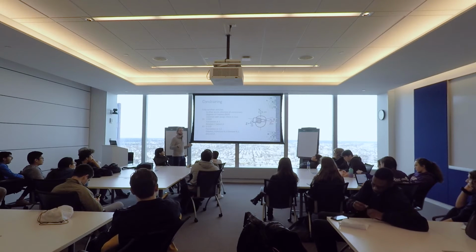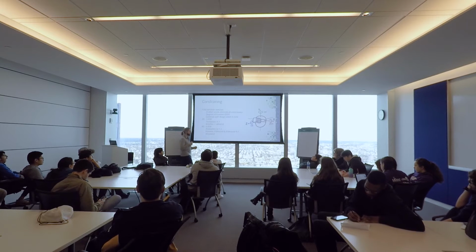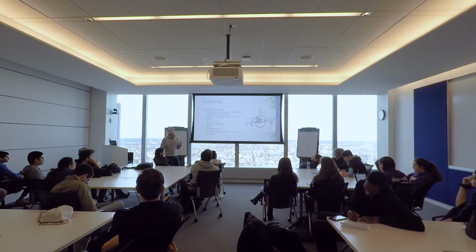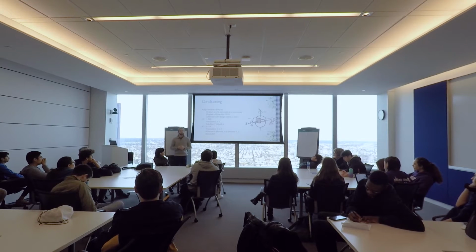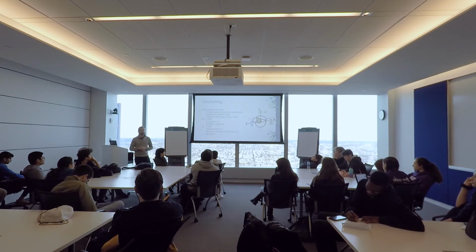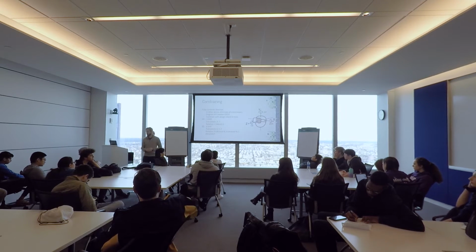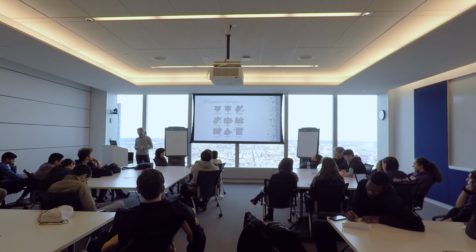In Onshape, sketches that are unconstrained or under-constrained are blue. Lines become blue or points become blue. And when fully constrained, they become black. And in SolidWorks, I think it's the same thing or something similar. You can change it in SolidWorks, so you can change whatever colors you want to be. I think stock gets blue and black as well.